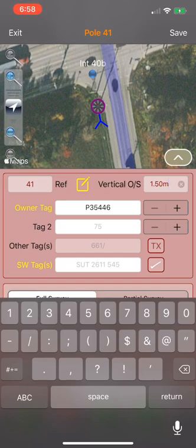The only time I don't do it is I might set my vertical offset default to 0 or just turn it off if I'm in a city and the entire project, the poles are at the street or coming out of the sidewalk, because you can clearly see that point where the base of the pole hits the grade level. And that would be the only instance.